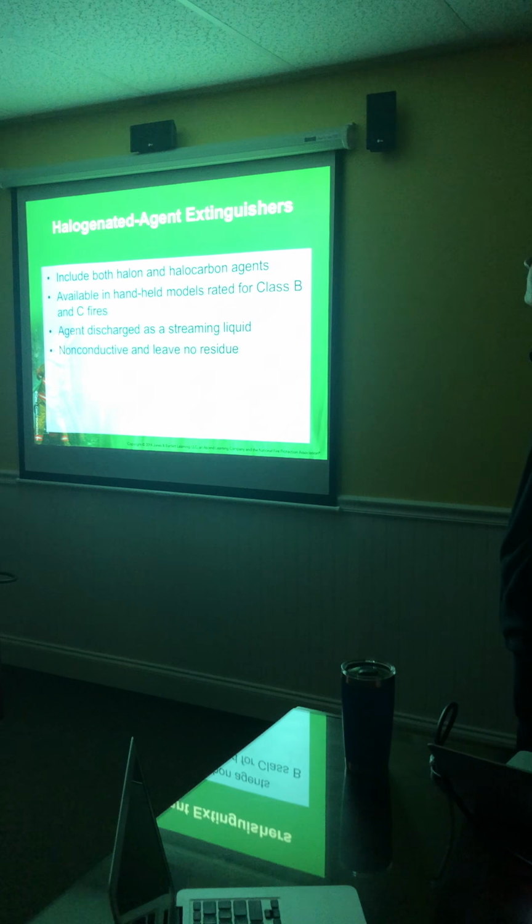Halogenated agent extinguishers, they include both halon and halocarbon agents, available in handheld models rated for Class B and C fires, and then the agent is discharged as a streaming liquid. They're non-conductive and leave no residue.